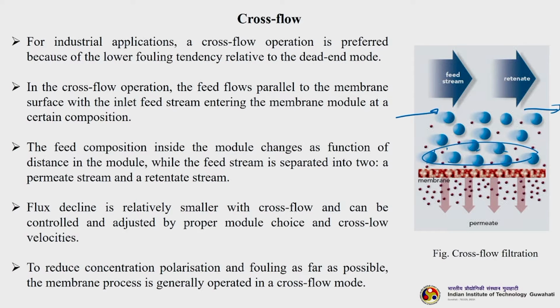So, that is why we have discussed that one of the techniques to reduce concentration polarization and subsequent fouling is to increase the feed flow rate. But every module and membrane can withstand only up to a certain limit of feed flow rate, so I cannot go beyond that. Five meters per second, six meters per second or something like that. Every module has certain restrictions, so up to that we can go.